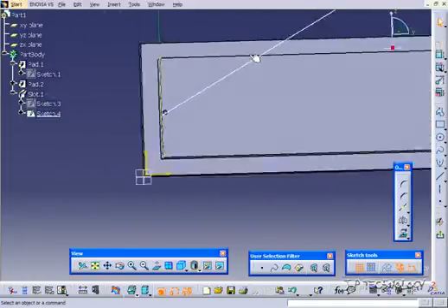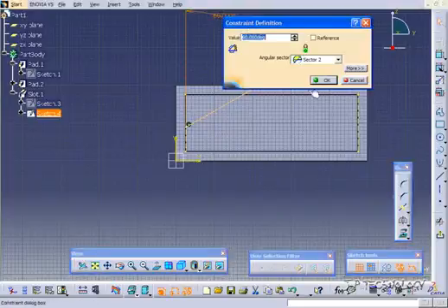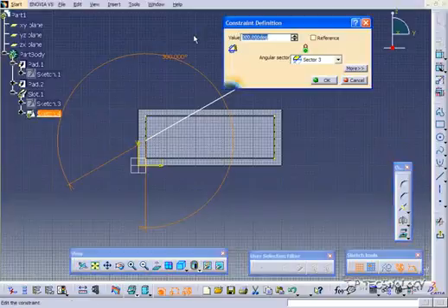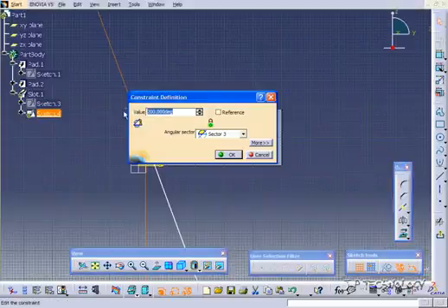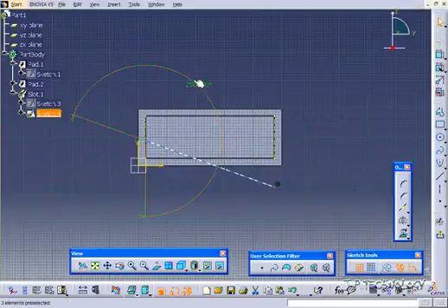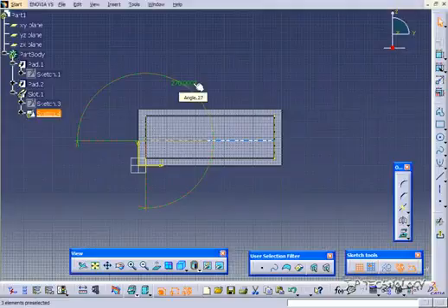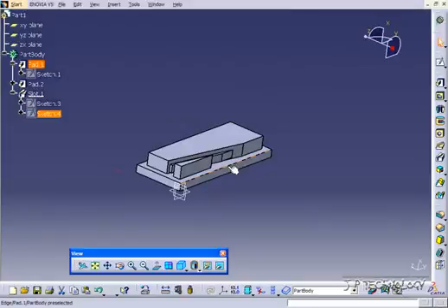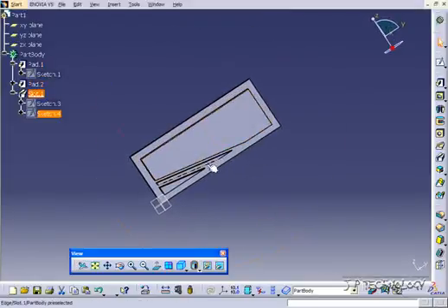Double click on Sketch 4 again. Right click on it, or double click on it, and we'll change the sector. Let's put it to sector 3. And let's bring this angle, let's try it at 200 right now. And that's not going to work, so let's bring it up a little bit more. Let's put it to 250. And bring it up just a little bit more again. So we'll bring it up to 270. Let's put it down a little bit more, 260. And we'll go back. And again, we've cut it on another angle. So you're able to change the path as much as you want.